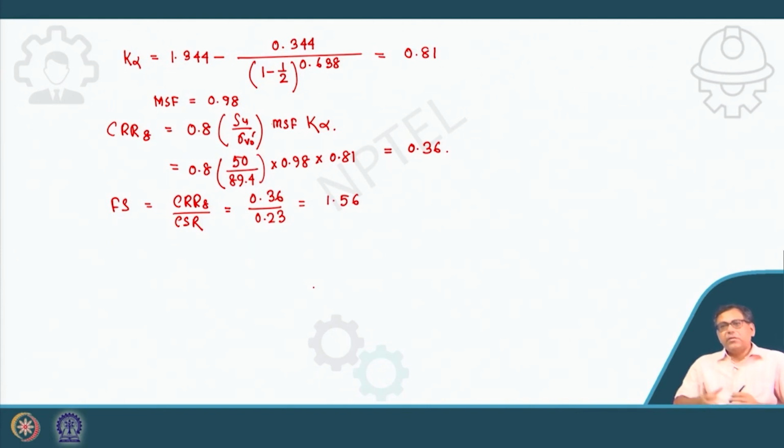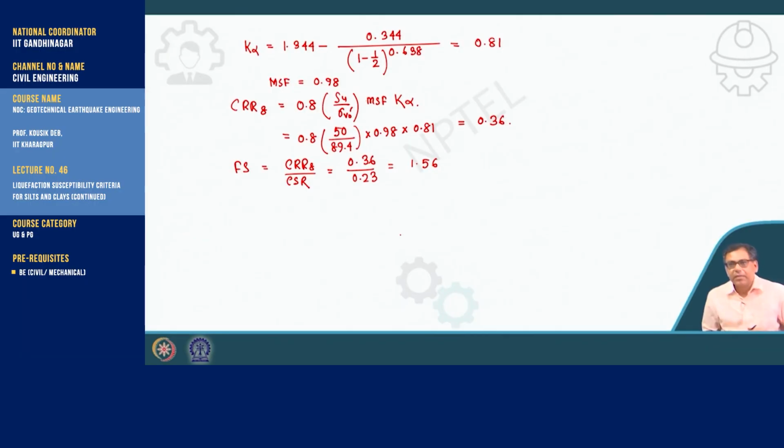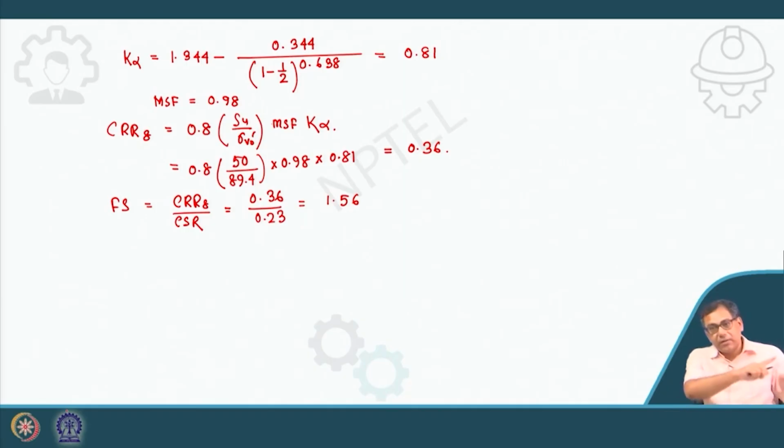okay, that means it is important to consider that building stress when you check this cyclic softening. Okay, so here we are checking the cyclic softening. So you can do it considering the building load, because there will be a K alpha, and for liquefaction it is definitely you have to consider if the soil is loose, isn't it?